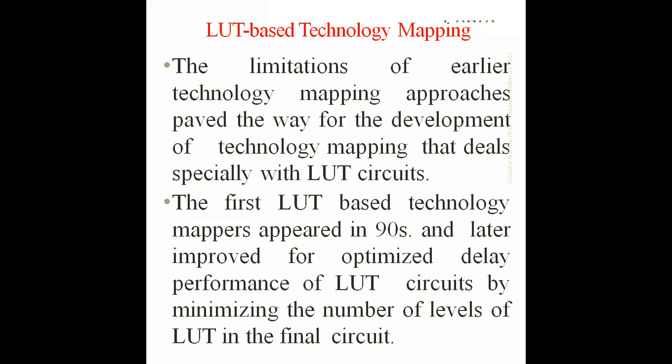Okay, next is the LUT, that is lookup table-based technology mapping. It is an important thing. One is LUT-based technology mapping, called lookup table-based technology mapping. The limitations of earlier technology mapping approaches prevented the development of technology mapping that deals specifically with LUT circuits. The first LUT-based technology mapping approaches came in the 1990s. They were later improved for optimized delay performance of a LUT circuit by minimizing the number of levels of LUTs in the final circuit.